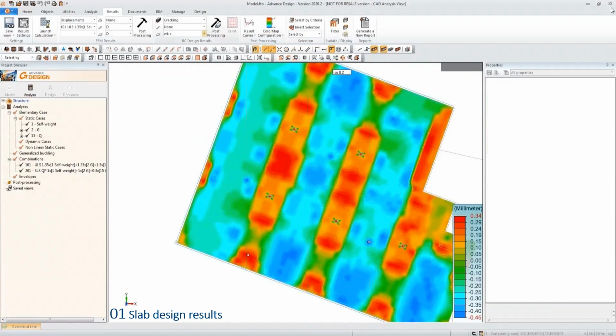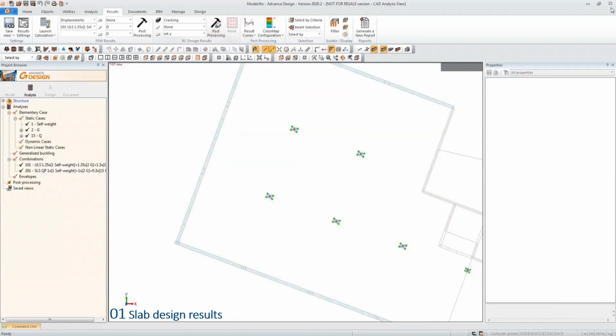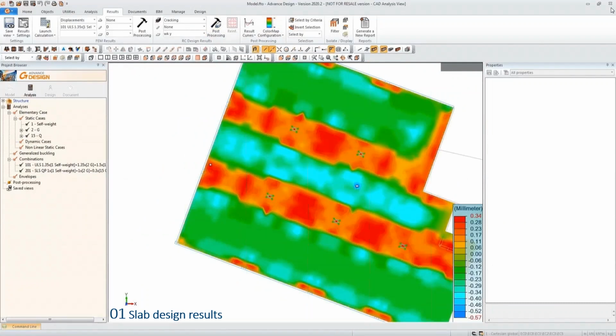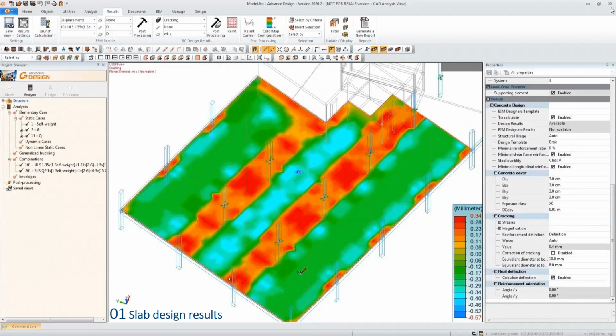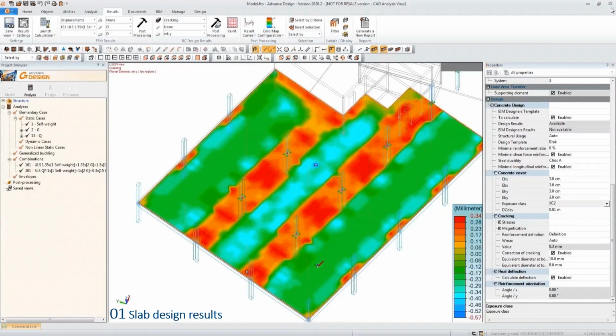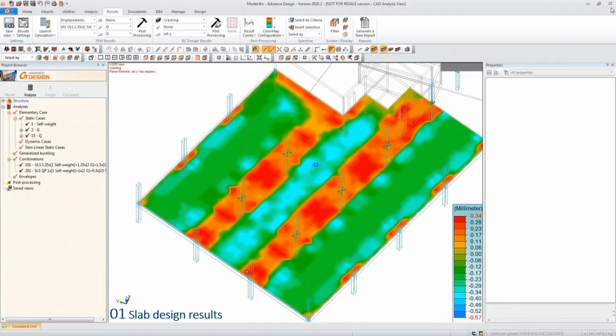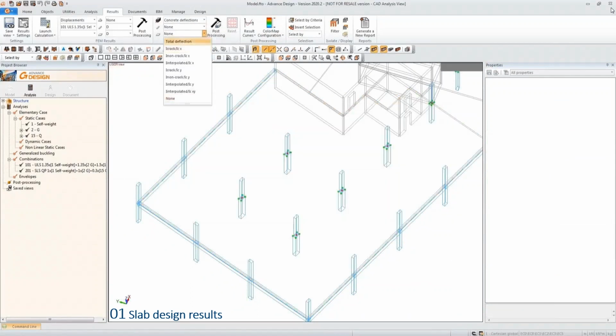I didn't do any correction to the crack, so as you can see, the crack width is nearly 0.6 millimeters. So that's not enough for me. I need to use more reinforcement actually. But for the calculation, I can set the correction of cracking. So the theoretical reinforcement would actually be provided enough to fill the crack.